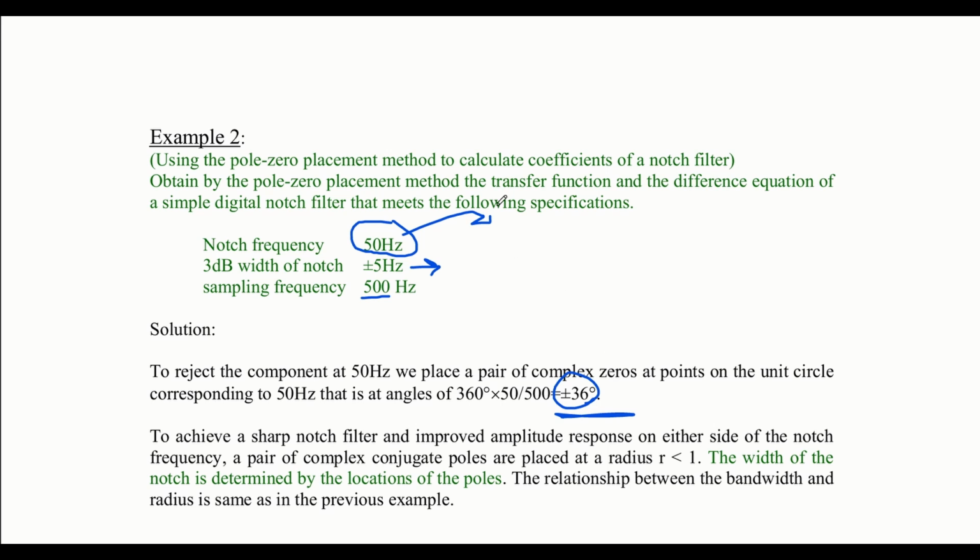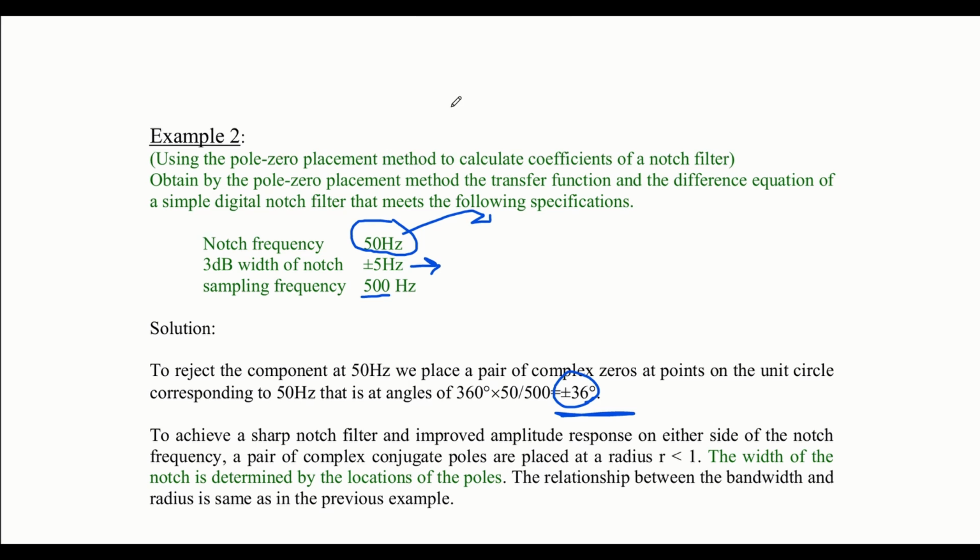And it's actually simple to get a pole for the notch filter. You remember that in the pass band filter, you were strictly defined the frequencies at which you are supposed to see zeros and the frequencies which you are supposed to pass. They define it for you. But in the notch filter, you're only trying to eliminate that frequency, so you put your poles at the same place to just balance the zeros.